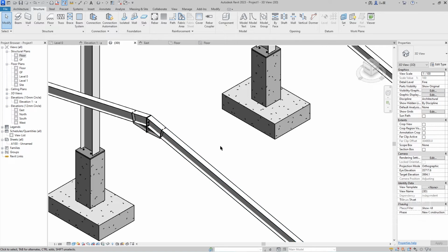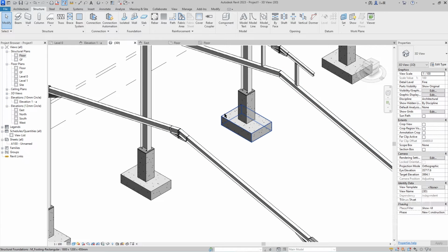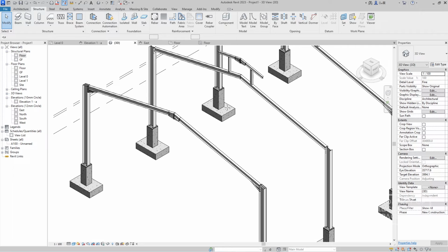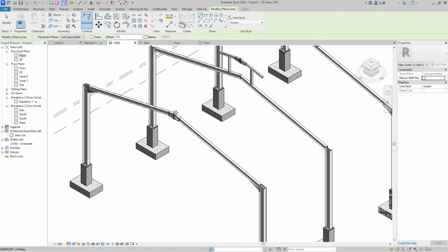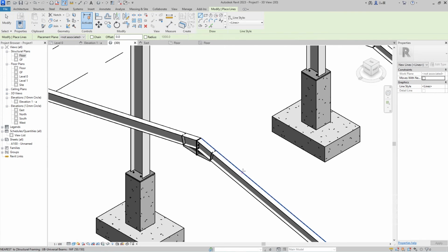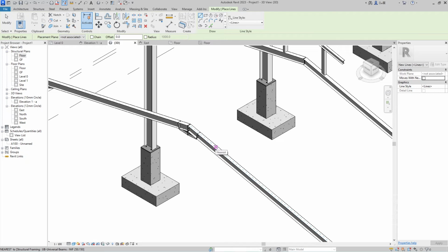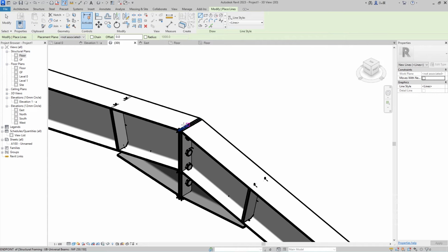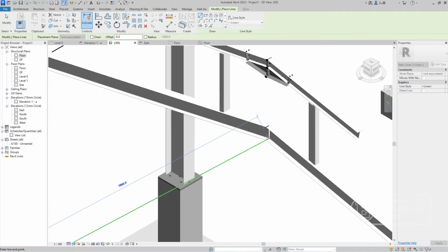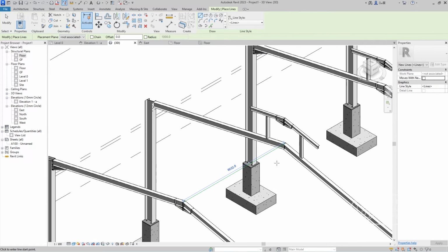So we're going to create a line from here to here, and after that I just type line or LI, and put the line from C, because this is 18,000. We can divide it into, let's say, 4 sections. First of all, I would like to take the center point and bring it from here to here, just like this.